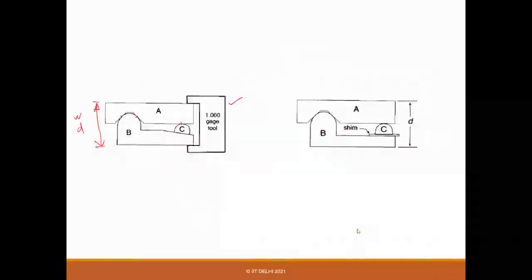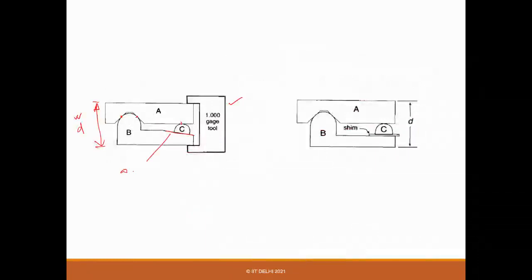So every time we do, what is the extra thing done here? This slope. And this slope is basically for adjustment. So what it does is, these three contacts, exactly the way it's designed, you can achieve an exact constraint design. It means you can get high repeatability. But providing this slope also ensures that this C can be moved.